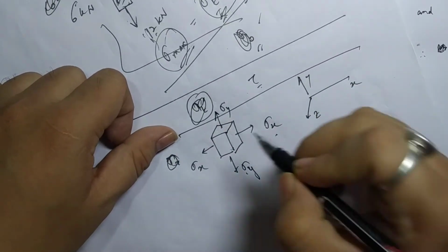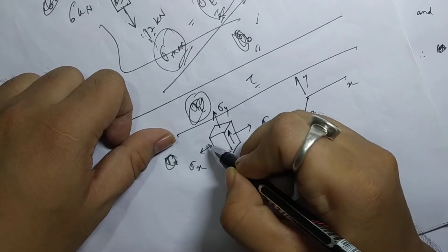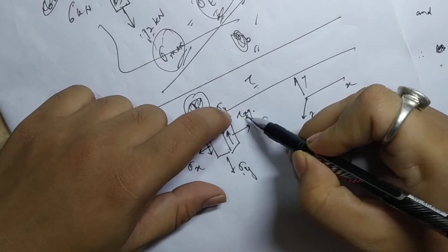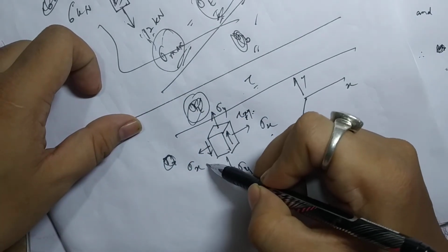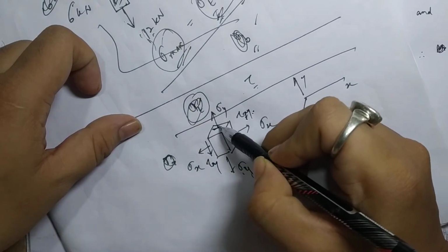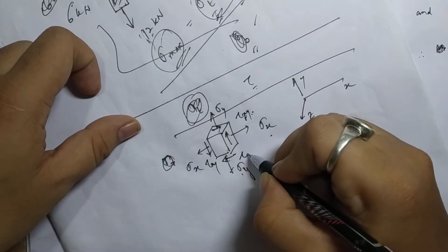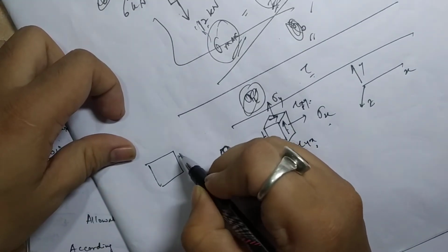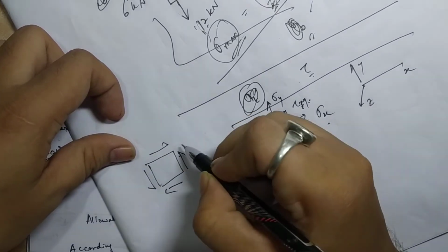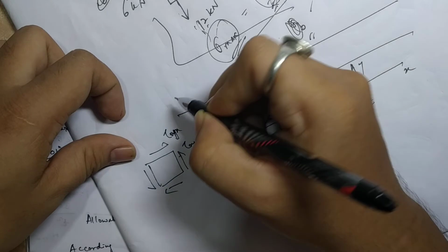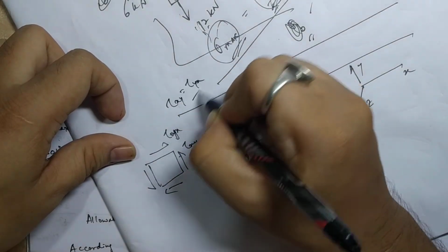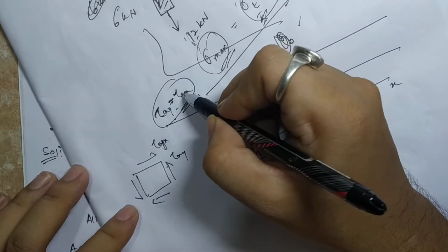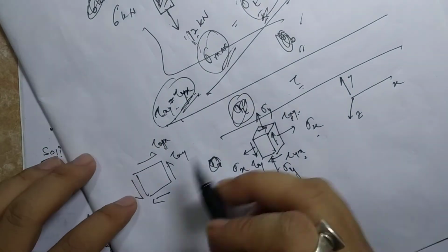They are applied stresses. We'll obtain principal stresses from them. Shear stress is also applied like this, tau xy, perpendicular to x direction and parallel to y direction, xy means. Here also there will be another shear, tau yx, perpendicular to y axis and parallel to x axis. You already know these from your strength of materials problems. Mathematically tau xy and tau yx are conjugate, they are equal to each other. Their magnitudes are equal.